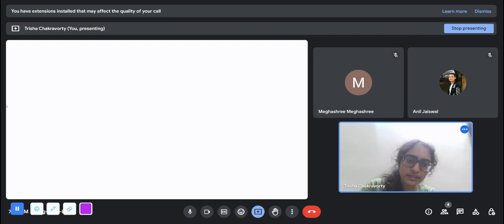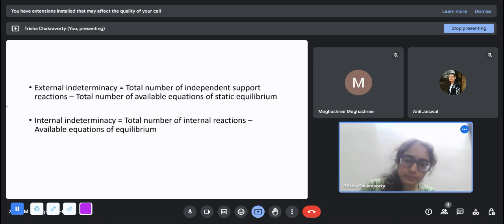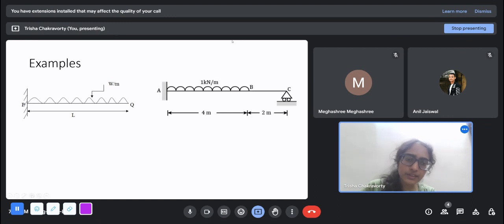So, for example, just for example, take this propped cantilever here. This vertical force, you can call this a redundant force, because if it wasn't there, this would still be a proper, stable cantilever beam. So you can take this RC as a redundant force.